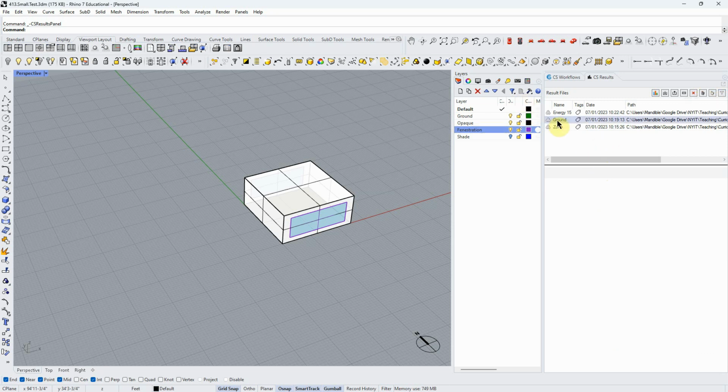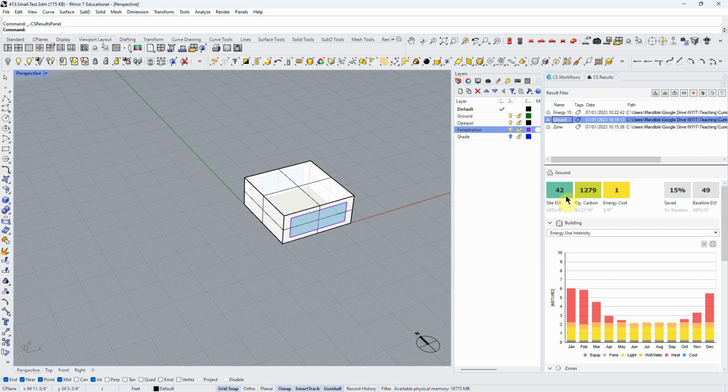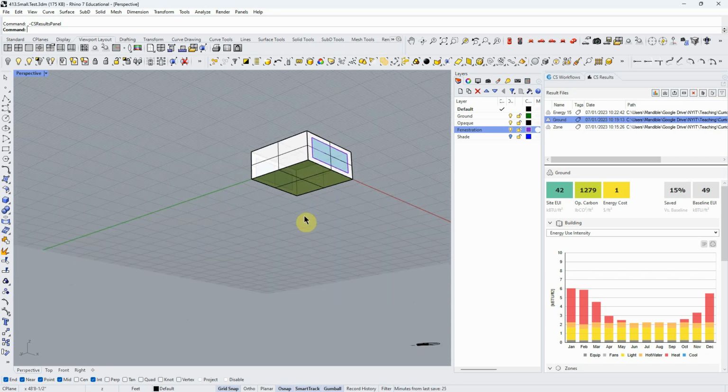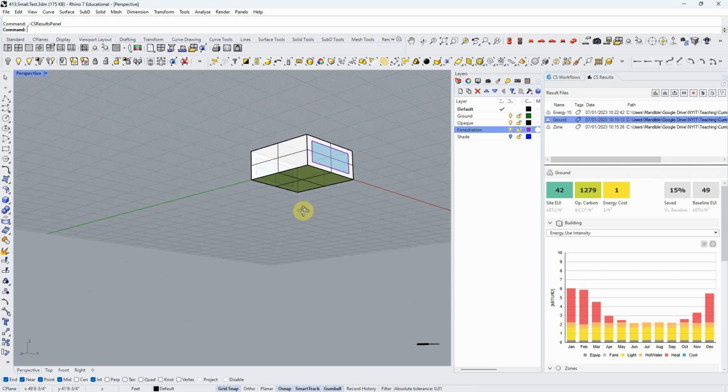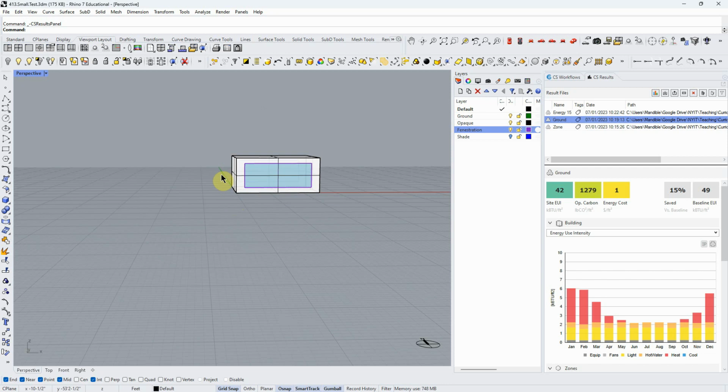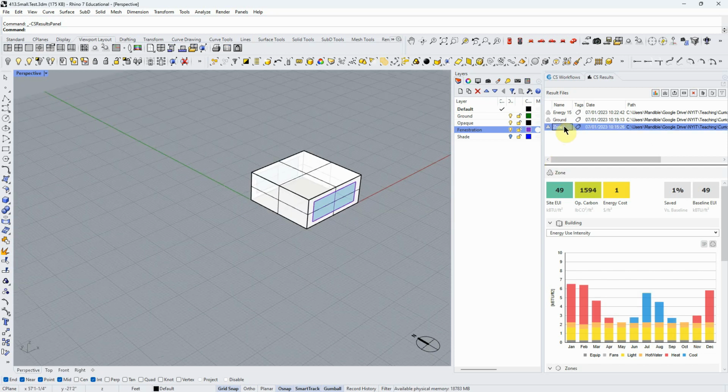Anyway, in the ground, it's lower because if we're not exposed to air and we're touching the ground, we could lose heat through it at a time we don't want to, but in general, it's a much more stable temperature at the ground level. The ground itself, even though it's not the 68 degrees that we would want, is say 55 degrees pretty much year round, maybe with some fluctuation. But that's going to be less heat loss than the air around the building, right? So that's why that changed from 49 to 42.